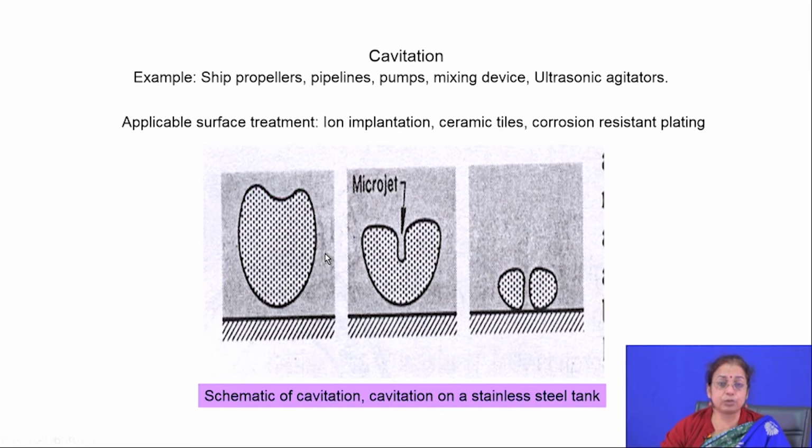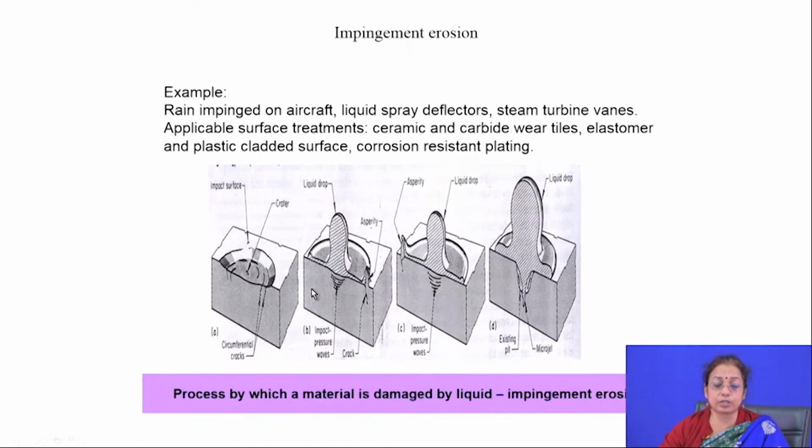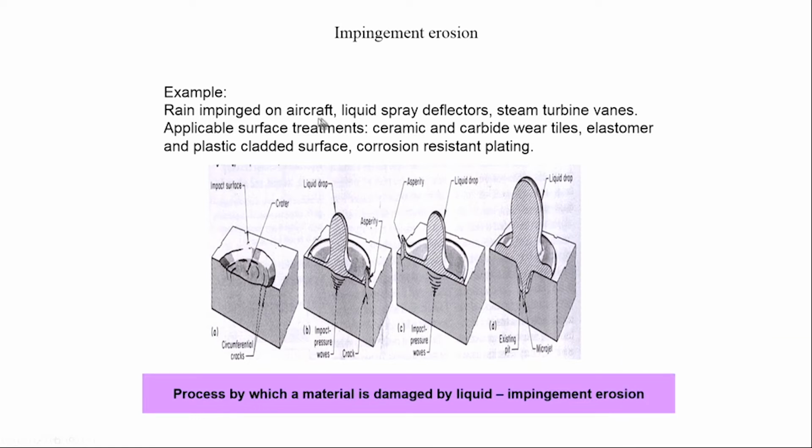So, these are the two different types of corrosion. If you see the surface after the liquid impingement process, you will find deep holes on the surface, and there is also subsurface crack formation and failure. Depending on the subsurface failure, the liquid particle may impinge and subsequently cause degradation of the material from the below-surface region.